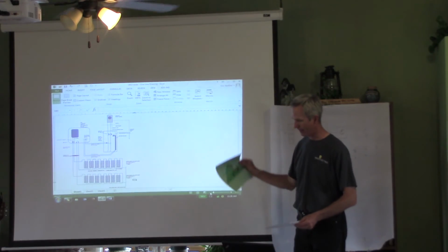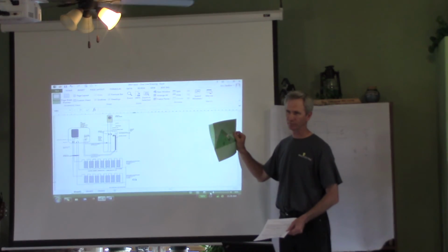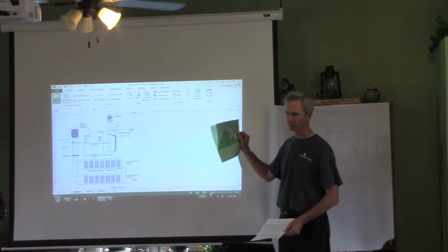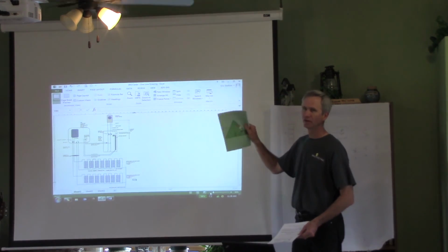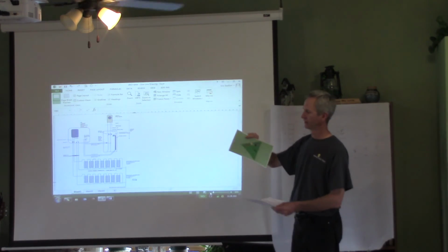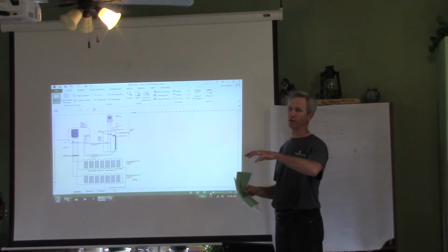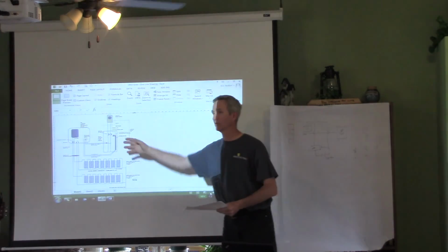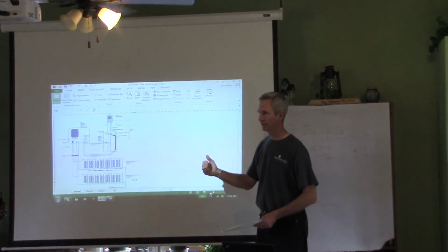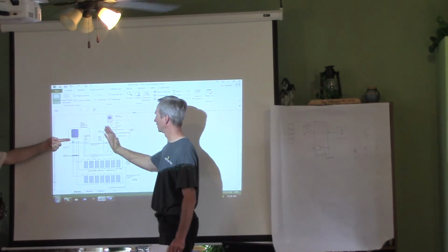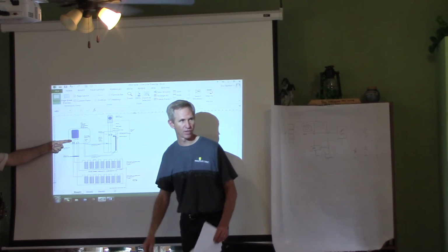I think I gave you a lot plan. I had that just in case because I figured I would need it for building permitting and land use and zoning in the township. I don't remember if I had to give this to Alliant Energy or not. Yeah, I did have to give this. Alliant Energy requires a site plan with disconnect. If you notice on the printout, it says down here, solar array with disconnect. So they wanted to know where the disconnect was. The Danfoss inverter actually has a switch on it that is the disconnect. What that means is they want to know that you can go up and cut off the solar system from that disconnect.